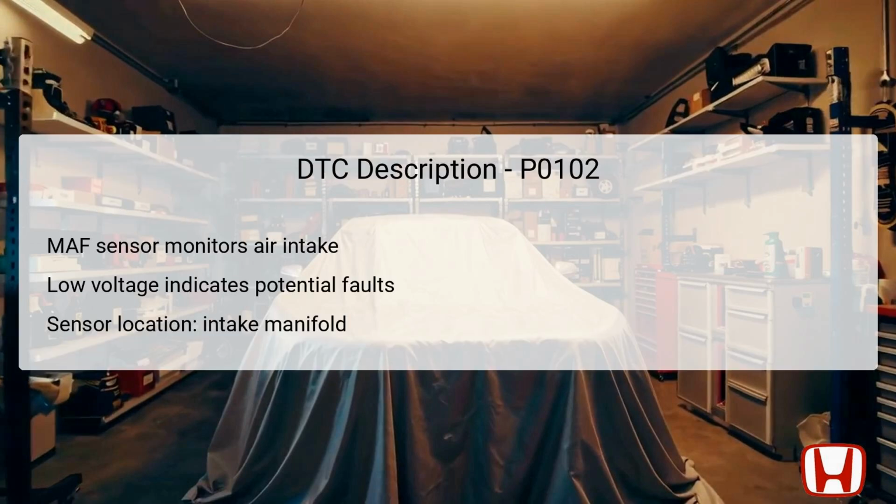The MAF sensor, or mass airflow sensor, is a critical component in the vehicle's fuel management system, directly tied to the engine's performance. When it detects a low voltage condition, as indicated by DTC P0102, it suggests that there may be an electronic issue related to the sensor circuits, potentially leading to engine performance problems, such as misfires or stalling. Located in the intake manifold just before the throttle body, this sensor measures incoming air, allowing the powertrain control module, PCM, to adjust the fuel mixture for efficient combustion.